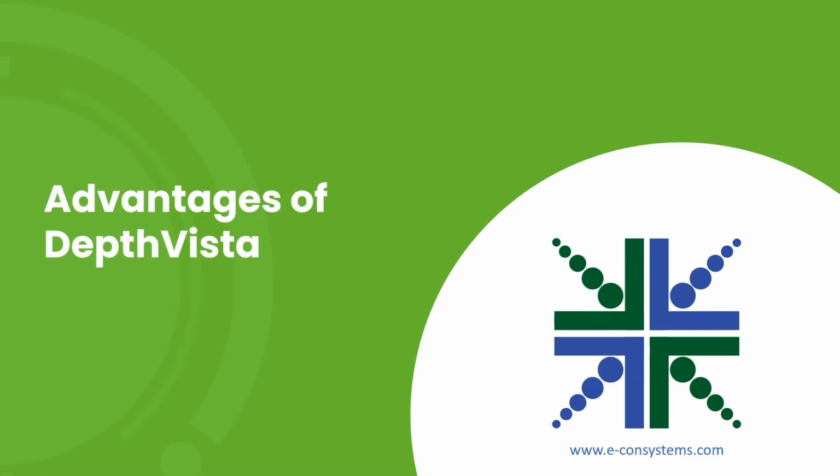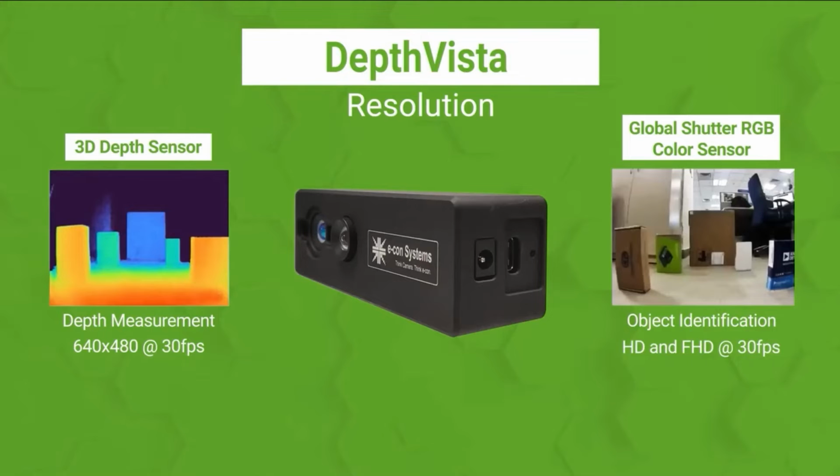Now, let us look at the advantages of DepthVista over normal ToF cameras. Depth sensors like LiDARs and ToF cameras use lighting techniques to create depth maps or 3D maps. However, for depth measurement, color information is not required by these systems. Also, adding it would increase the computation load on the camera systems as well. For these reasons, an ordinary depth camera does not come with the option to deliver color or RGB data.